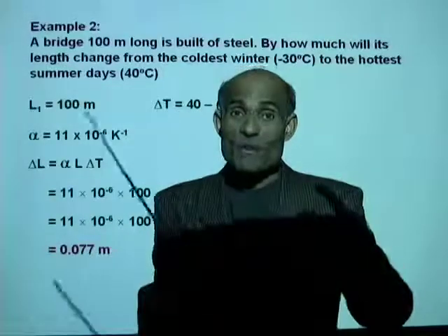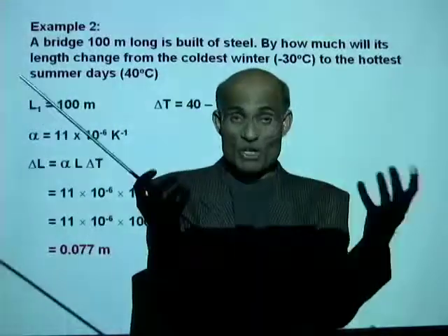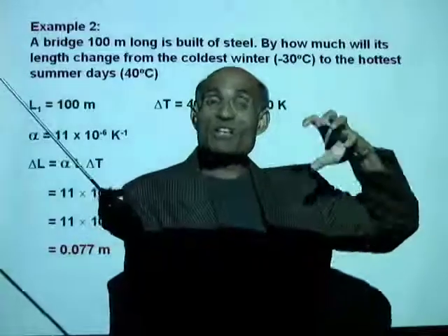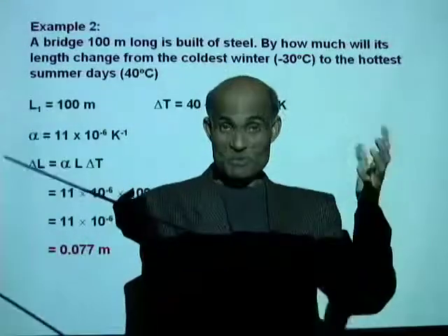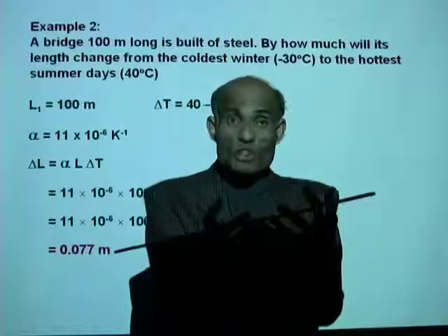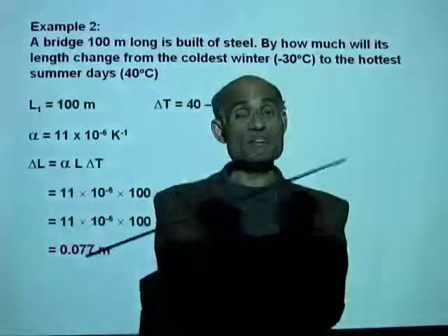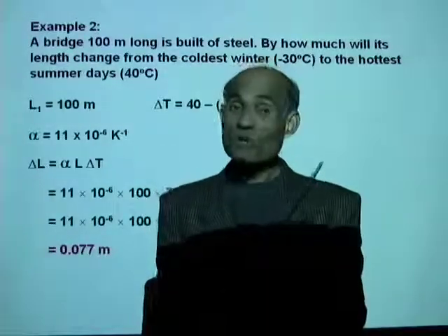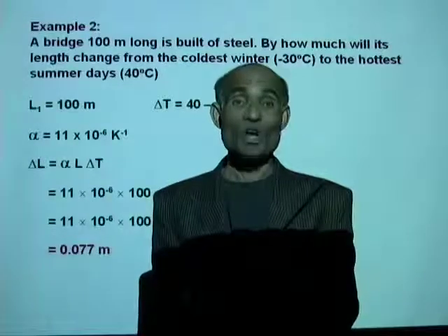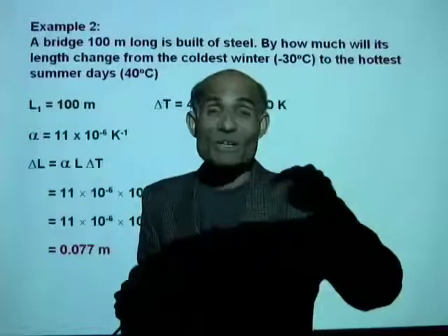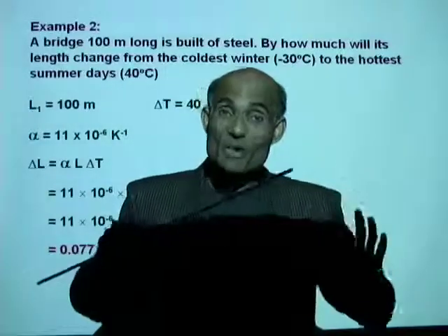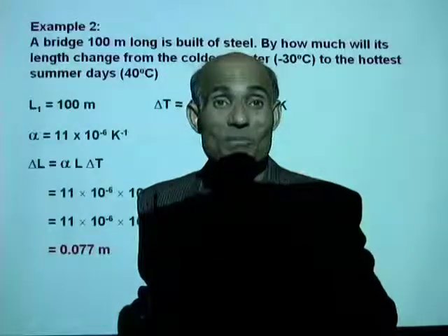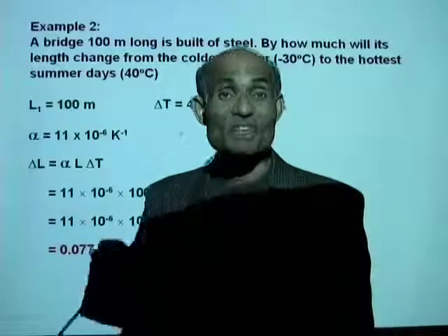We break them into slabs and allow a space between them. Why? Because when temperature increases and decreases, cold winter to warm summers, there are tremendous changes in temperature, especially in Florida. That means the concrete slabs will be expanding and contracting. We got to allow space for this to happen. And if you don't allow space for this to happen, the concrete will crack. Now, if you look at some driveways, you can see those cracks where those spaces were not properly provided. So all these have great application in building industry, in civil engineering.